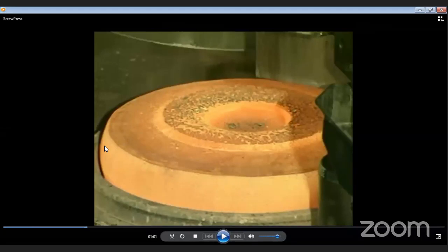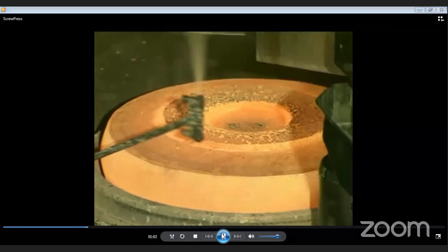Okay. So further, while considering design considerations, means design parameters, an important parameter for the forging process is called the draft angle. Here there is a taper. Here also you can see tapers. So all the faces have some tapers. This is called a draft angle. We will see what a draft angle is and why draft angles are provided in the component or dies in the presentation. But just understand the feature of how the draft angle is.